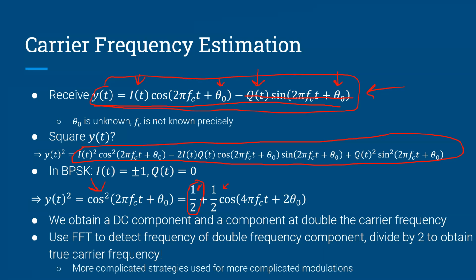Before you demodulate this and obtain your baseband representation of your modulation, you have to know the carrier frequency. So what you do first is obtain a packet of information, which contains some number of symbols, and you perform this entire algorithm on that packet.